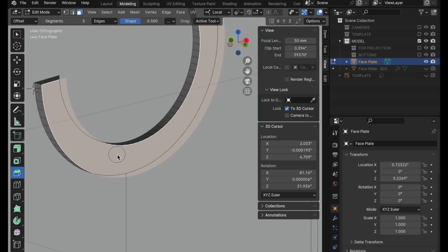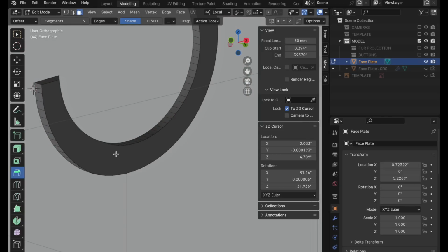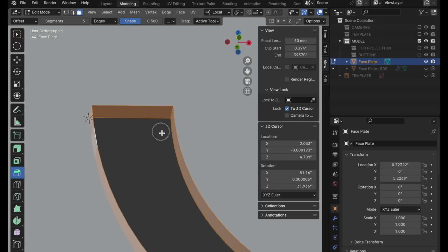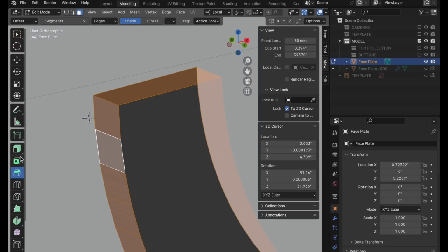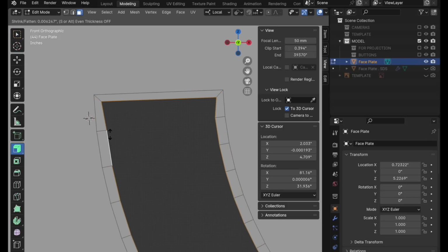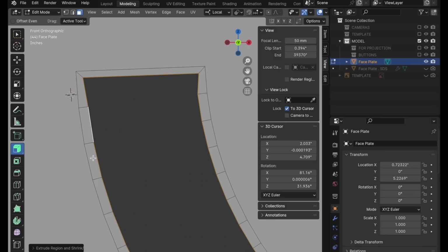I will delete this bottom polygon because we can regenerate that. Press the X key to delete faces. There we go. Now double click to select this inner boundary loop, and we're going to come over to the extrude along normals variation. In fact, let's look at this in the front view. Click, hold, and drag, and we're going to pull in just about that far. So this will also produce that boundary loop that we need, the planar boundary loop.